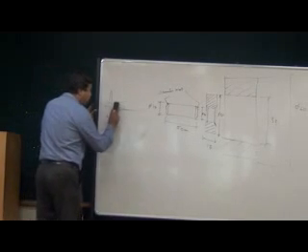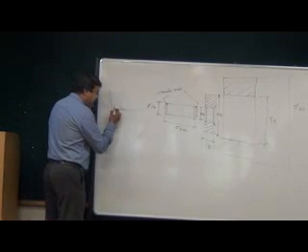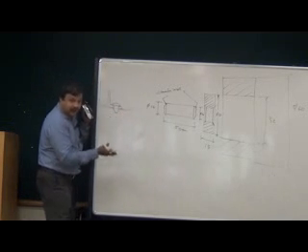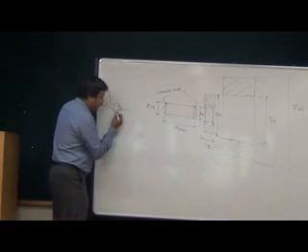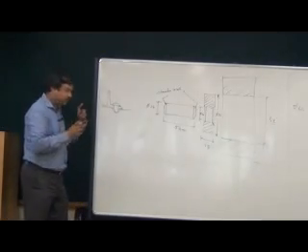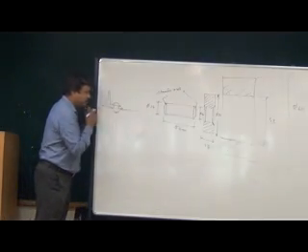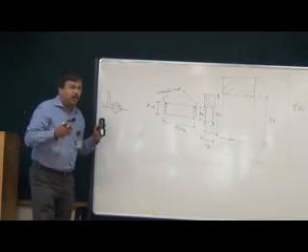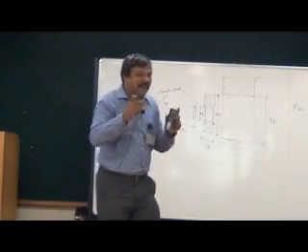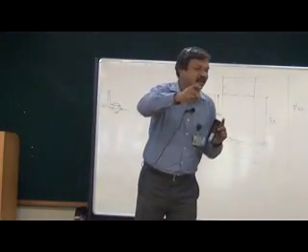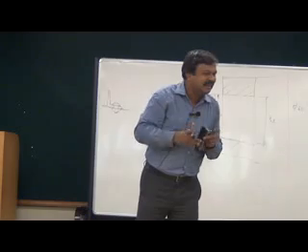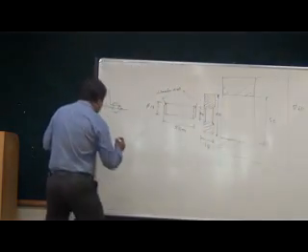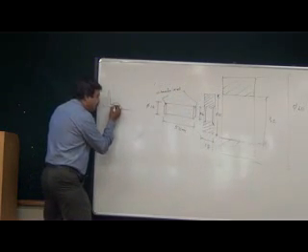You first make a hole, and it will become something like this. For easily assembling the rivet, the hole must be slightly larger than the rivet diameter, is it not? So here there will be some gap.